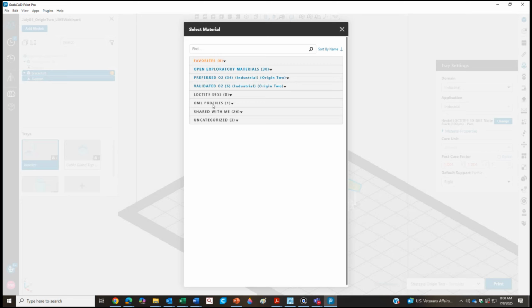OpenAM lets you expand your printing options in several ways. First, more material parameters are unlocked for editing than the base settings in the already well-populated P3 material library. Or you could explore and optimize the build profiles of any resin of choice. This license gives power users access to advanced printer settings within GrabCAD Print that let you tweak parameters such as UV exposure level, build chamber temperature, build plate motion timings, and more. These next level settings are perfect for fine-tuning specific materials or improving throughput.